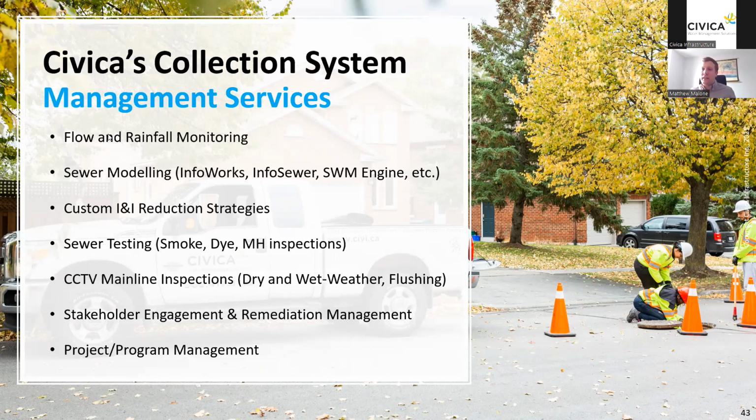But ideally, if you look into some of the literature, Environment Canada has some guidelines. There's another French one that I can send you as well, where they have class 1 through I think 4 in terms of siting for rain gauges. So class 1's like best situation, best location, down to class 4.